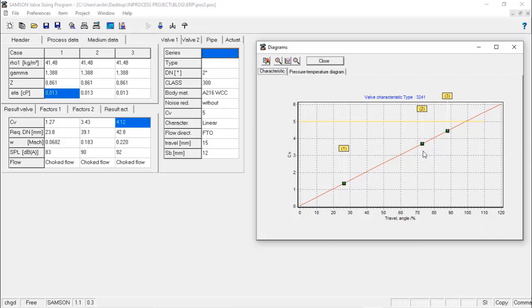You don't want to control a process at 100% open valve, because if you are doing that, you are not controlling anything. And normal flow, we are closer to 50 and 70 range, and at the lower flow I have around 25% open, and so this condition is okay for me.